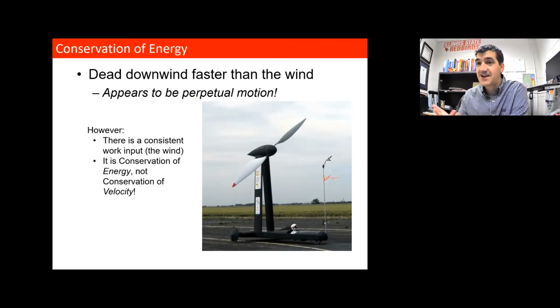It's a drag device. I mean, it's being dragged by the force of the wind, but then also the propeller is being driven by the axle of the wheels. One way that it might be confusing is if you think that the wind is acting on the blades and the blades are driving the drive shaft to drive the wheels. That's not the way it's working. The power is going the other way. So it's actually getting up to speed, and then the drive shaft from the wheel is driving the propeller shaft, which causes the propeller to spin, which pushes it faster than the speed of the wind. It's kind of mind-boggling, but it really does work.